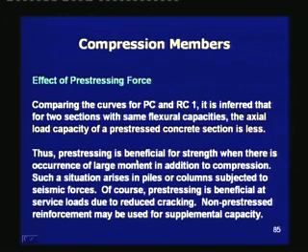Thus, prestressing is beneficial for strength when there is occurrence of large moment in addition to compression. Such a situation arises in piles or columns subjected to seismic forces. Of course, prestressing is beneficial at service loads due to reduced cracking. Non-prestressed reinforcement may be used for supplemental capacity.